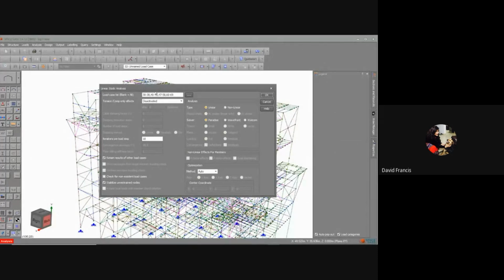I've done all of the combination load cases, and by the way, that is one of the most important things. You only work with combination load cases. Here in India, I've found many engineers working with primary load cases, and primary load cases do not exist in reality. Things like live load, your live load by itself doesn't work. Live load goes with dead load at least. And so the importance of the loads that you choose to design to. So when I do my analysis, these will be a series of combination load cases.